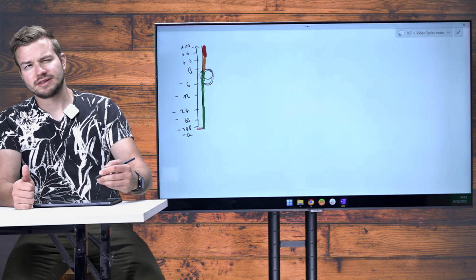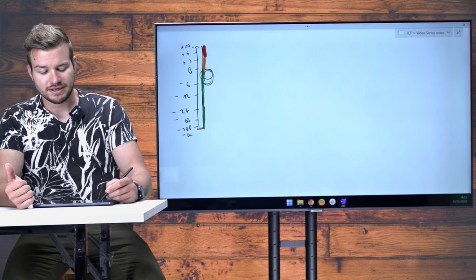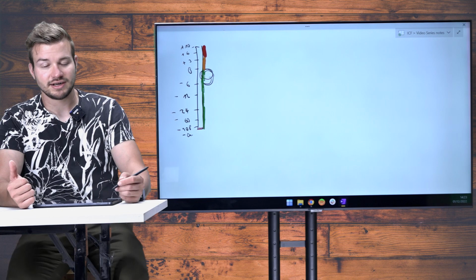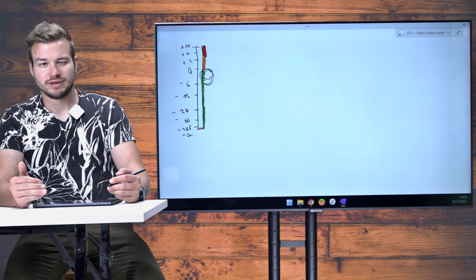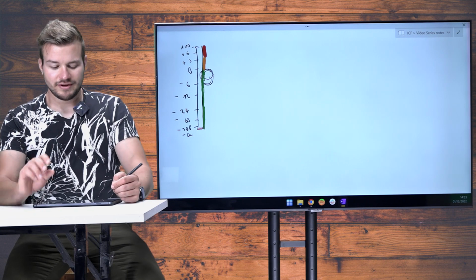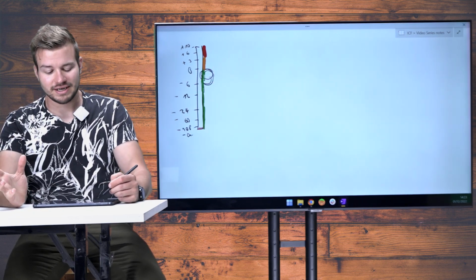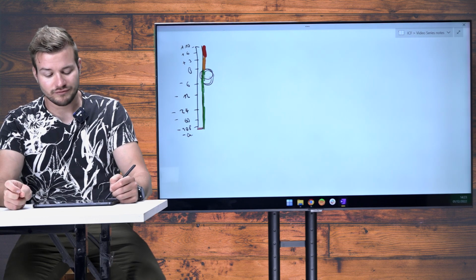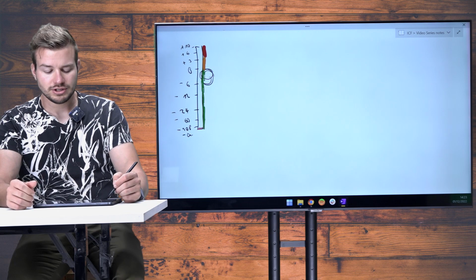Our goal is that the signal does not overdrive. When it is in the red area, it starts to overdrive, and we always want to make sure that doesn't happen. So when you set the channel gain or whatever gain it is, make sure it is somewhere in that green area, around -6 to 0.